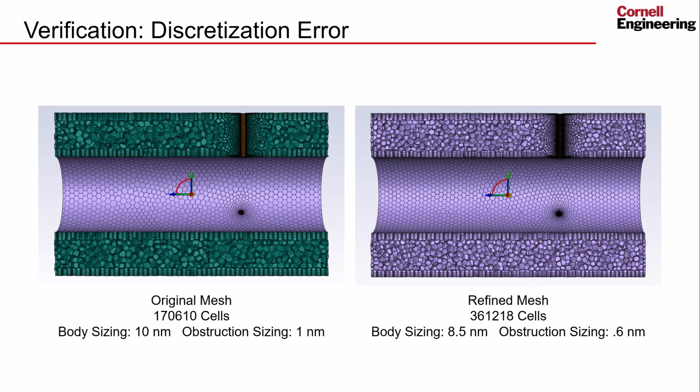Secondly, the mesh can be refined to contain more elements. This means the solver will find values of the primary unknowns at more points in the flow domain, and the discretization error will be reduced. This can be easily achieved by reducing the element sizes in the meshing step. Since our convergence criteria was already extremely small, this is likely to have a larger effect in reducing errors. We can expect the largest changes to be seen on the wall shear plot, since it is highly sensitive to the mesh near the boundaries.